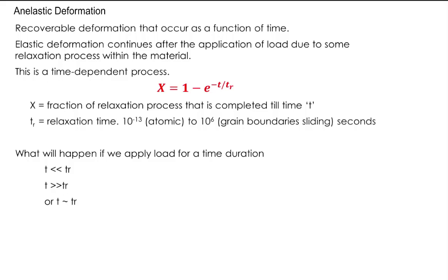In the previous lecture, we studied elastic deformation, which is a recoverable deformation, and it was time independent. Now we will study the anelastic deformation. Anelastic deformation is a recoverable deformation that occurs as a function of time.